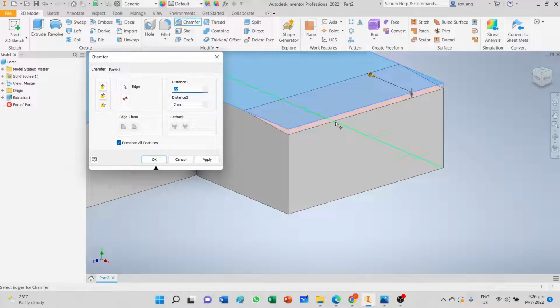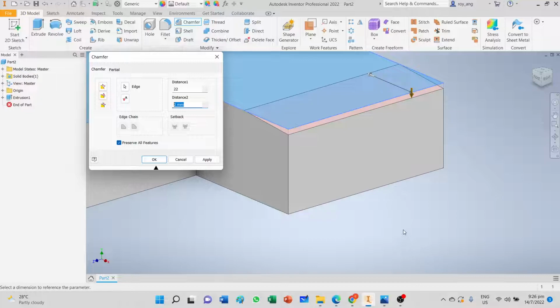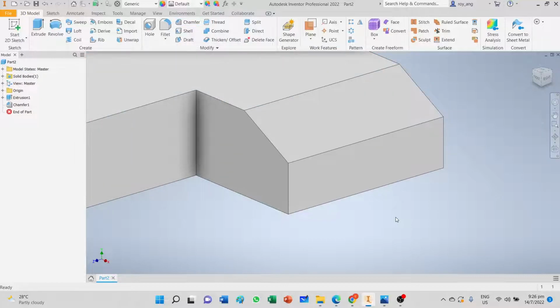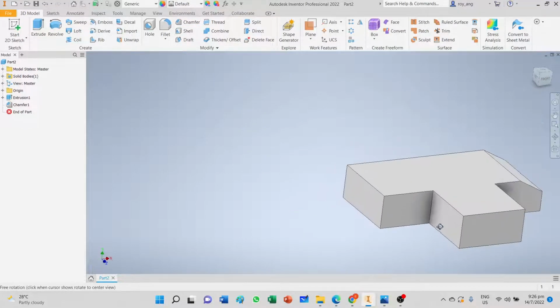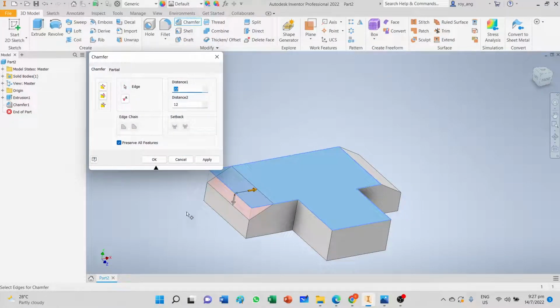And I know that this is the long edge that's 22 and that's the correct edge, so I change the bottom one to 30 minus 18. They didn't give you the direct dimension over here, so it's 30 minus 18, which gives you 12. So you need to enter the value of 12. Enter. And vice versa, you swing it around and you create the chamfer.